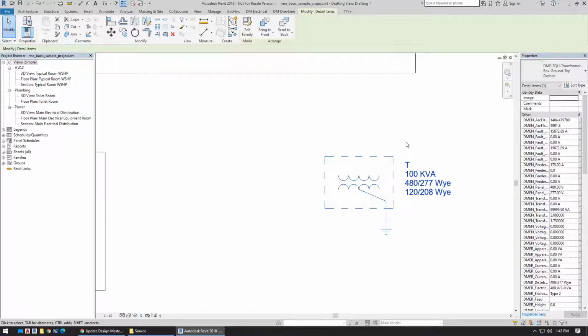So if you do 1 to 12, that way 1 foot is 1 inch. And when you go down to 1/10 of an inch, it's 1/10 of a foot, and things work out a little bit better. So we have basically everything scaled up by 12, and it ends up working better with Revit.